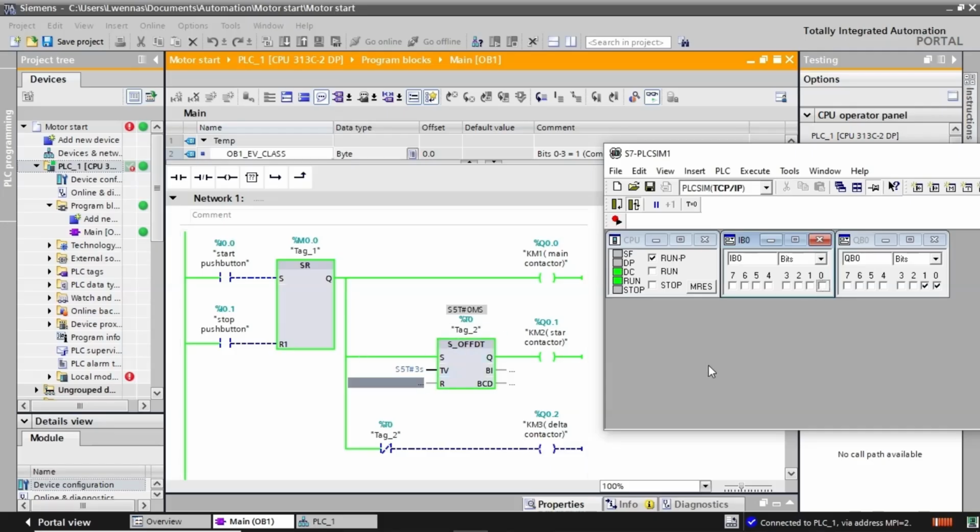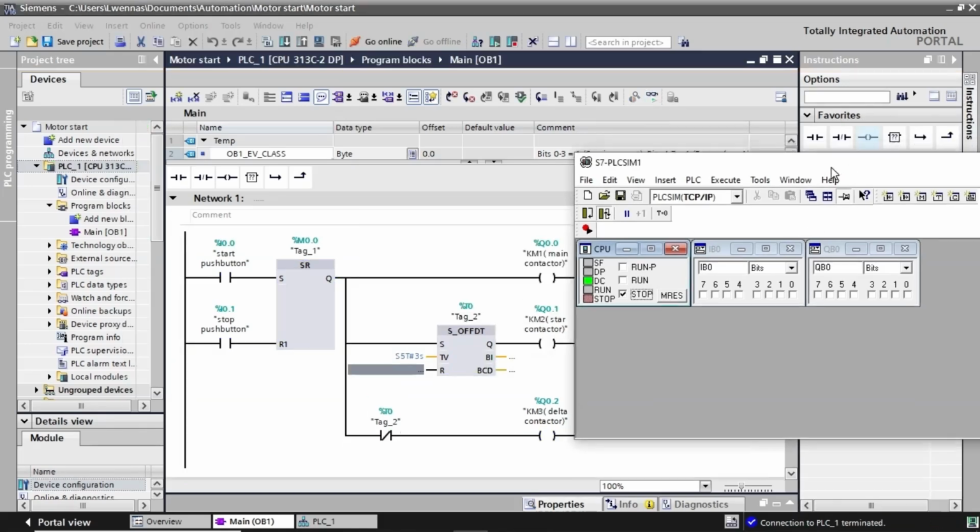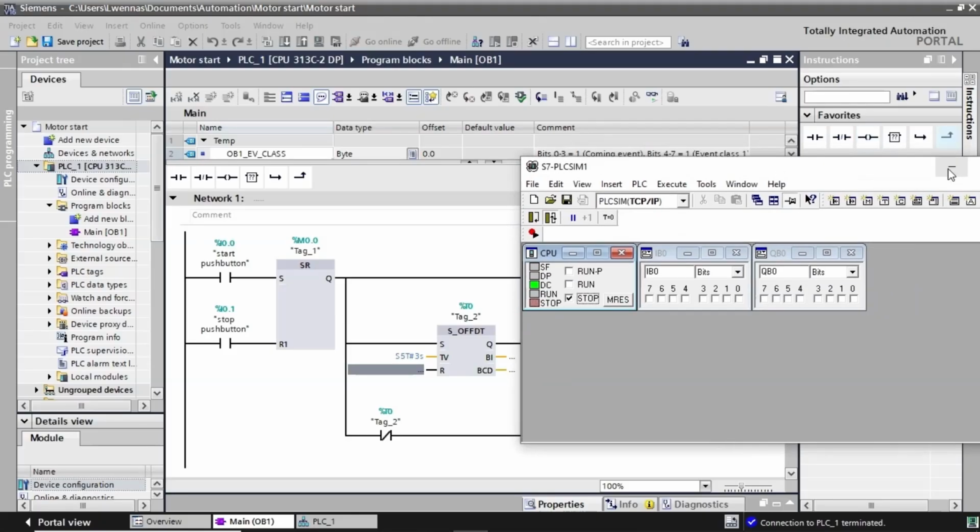As we can see, after clicking on the start push button, the program did not work the way we expected. Moreover, only when we deactivate the flip-flop with the stop push button does the timer start working, since the timer is activated with a negative edge, which is not appropriate for our code. As a result, all we need to fix the program is changing the timer. We get another one and see the results.